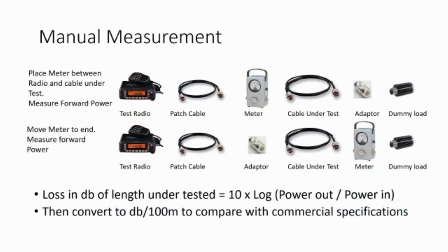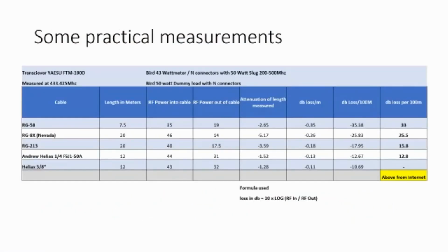So I went through this process with all of those cables: measured the power into the cable, measured the power out of the cable, and then calculated the loss in that piece of cable, converted it to loss per 100 meters, and then looked up the cable where I could to get the specification. So here are the practical measurements that I made.